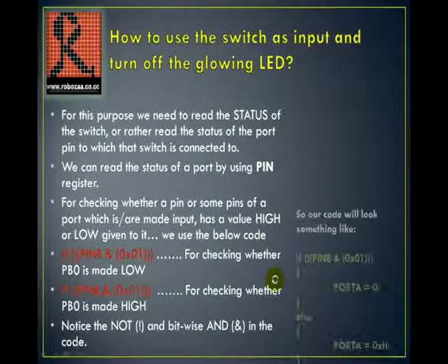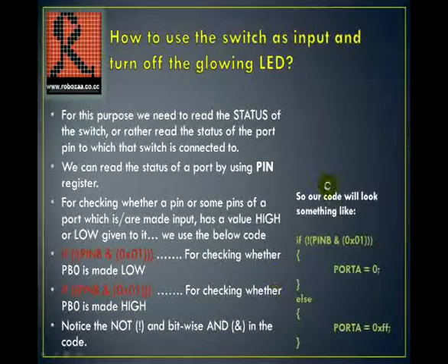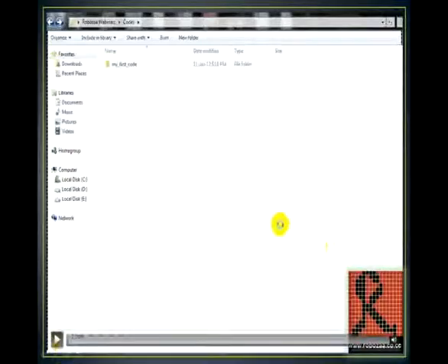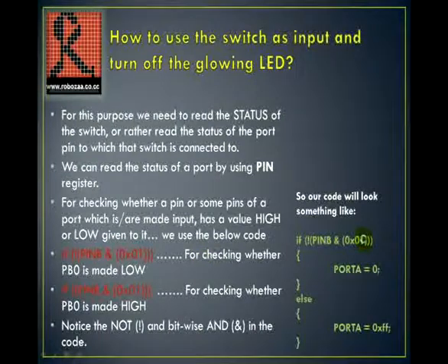So our code will look like this. If not PINB 0x01, then if this condition is satisfied, we will make the LED off by giving the PORT A equals 0 statement. Otherwise we'll give PORT A equals 0xFF so that it remains on.